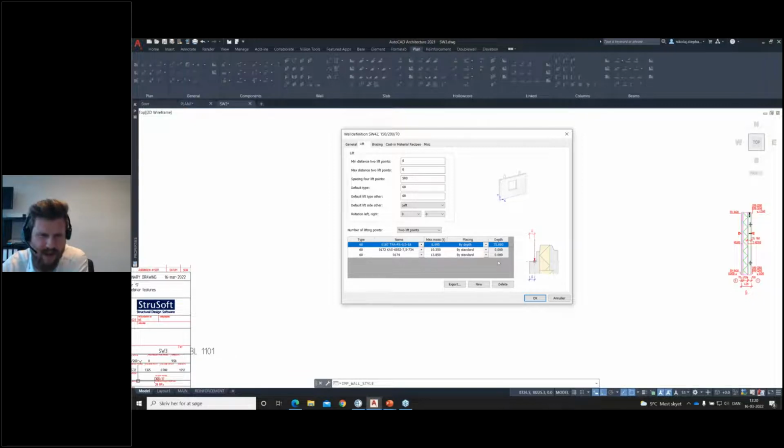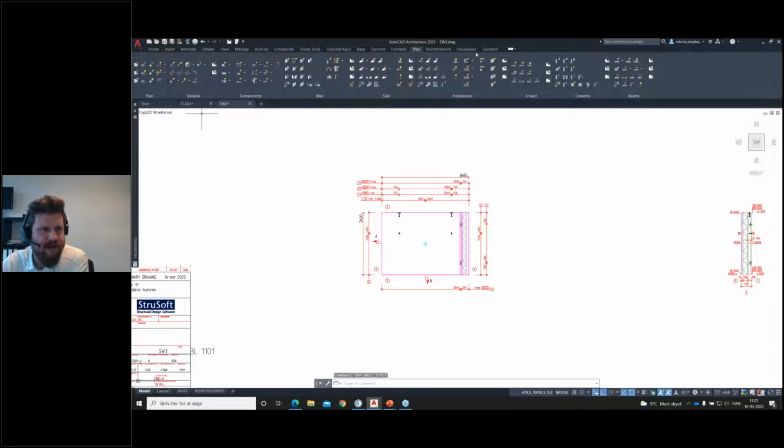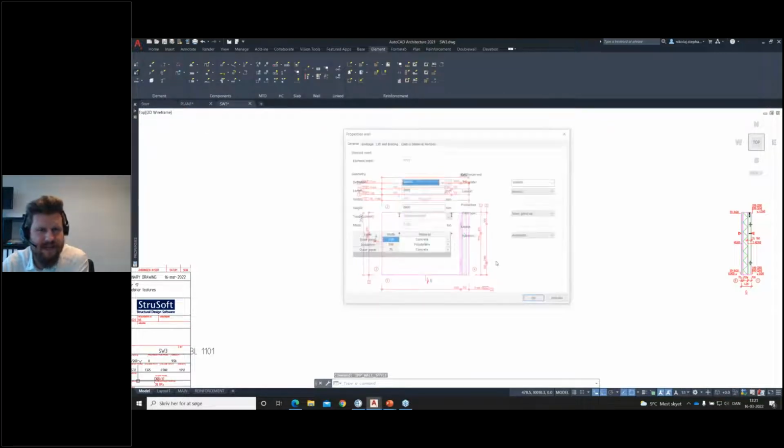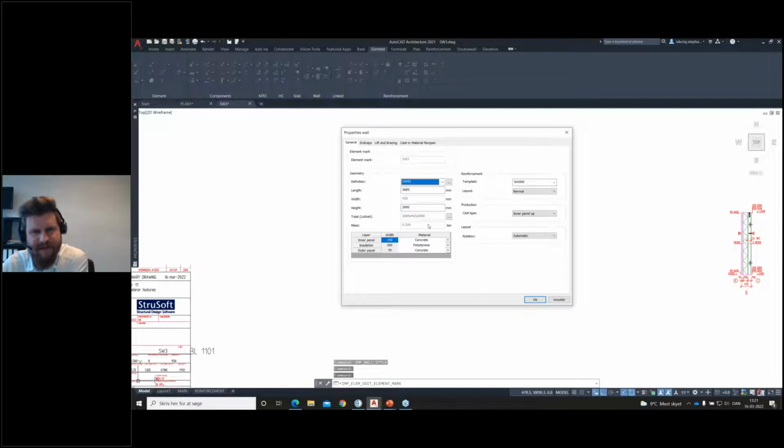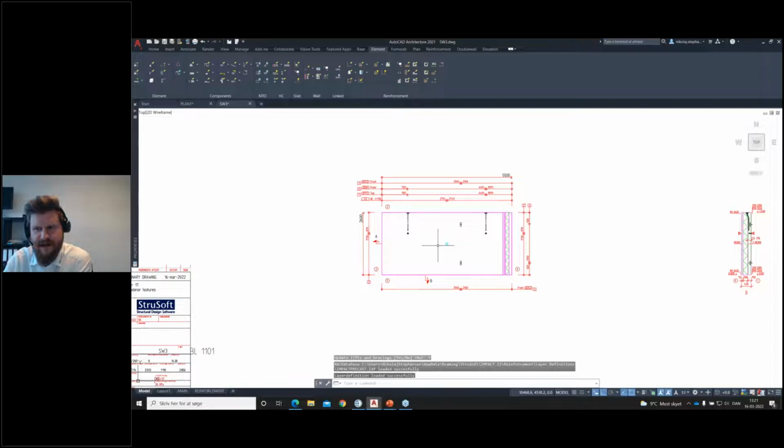So let's go ahead and change the element a little bit. What I want to do is make it bigger, because right now it weighs 5.3 tons. And as you could see before, when we hit those 6.9, it's going to do some changes. It's going to put some other lifts in. So what happens if we make it 5.5 meters instead? We're going to hit almost 8 tons. Let's just do it. Yes, please redraw and please update basically everything in this case here. And then when it does this, we'll get this new other type of lift.